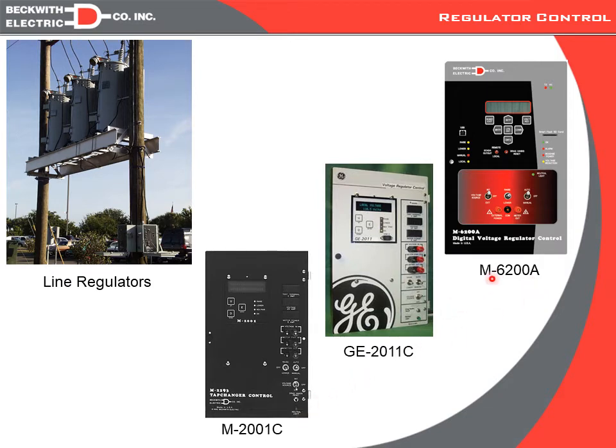It differs from the 2001 platform in that it is not to be used for LTC control, as it does not have any capabilities for paralleling of transformers. So it is less expensive, has similar functionality to the new 2001D, but is made specifically for single-phase regulators, and does not use the adapter panel concept of the C, but instead has an adapter kit concept that is handled in a different session of this presentation.